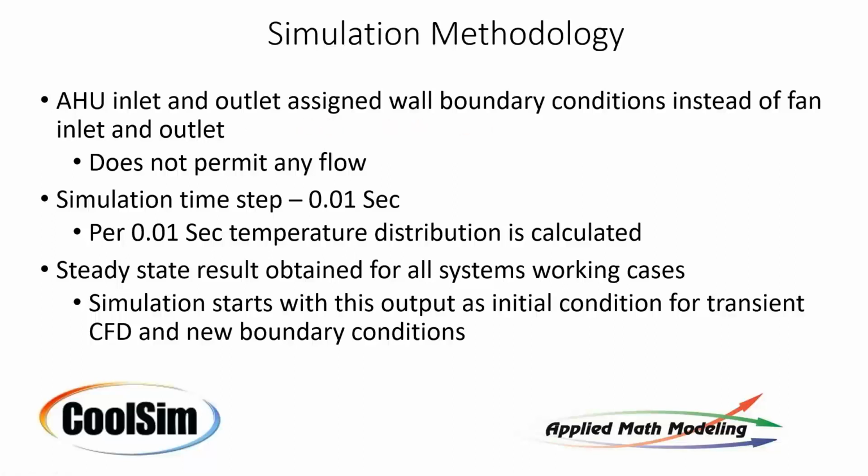Now, not quite true. They do leak a little bit of air, but not much. The fans are on, the IT system is really going to recirculate on itself. Once those fans go down in this design, because it is not contained, there's no pressure delta across the air handlers at all. So they're just not going to produce any cool air into the room. So we assigned boundary conditions of walls to them. We didn't let any air go through them.